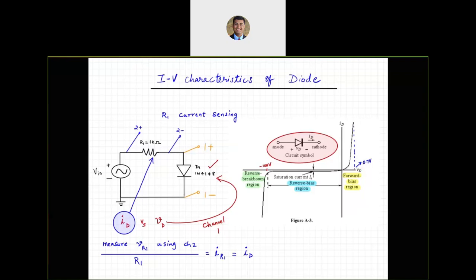So if you go a little bit more precision, like if you zoom in and actually find out what that limiting voltage is, it might be 0.71, 0.72, and all those details you can explore using the data sheet. But for the purposes of theory and equations, we are going to assume that it is 0.7. What I mean to say is we are not going to say 0.8 is a turn on voltage.